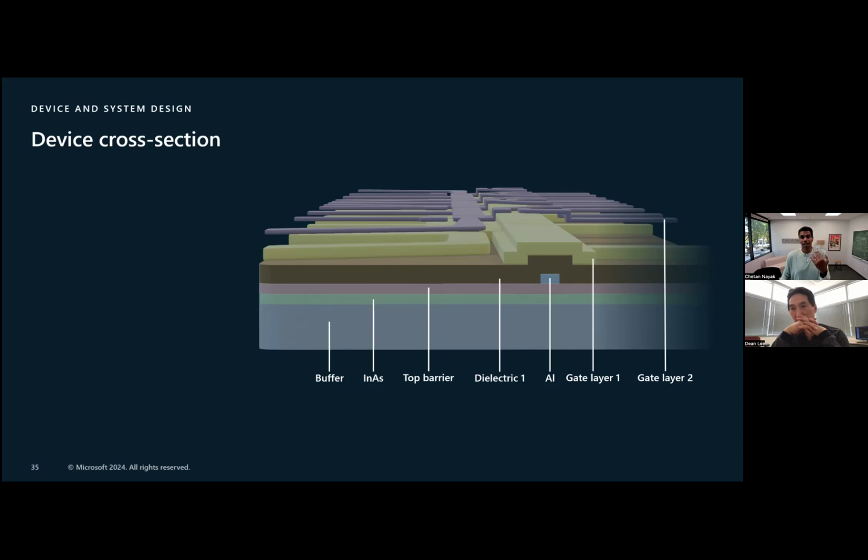So we need a healthy and robust interface that's relatively transparent, so that you can get electrons to hop into the superconductor and back. We want a lot of tunneling into the superconductor, but we don't want too much, because if the electrons spend too much of their life in the superconductor, then in the superconductor their g-factor is not 10, or actually it's not -10, it's +2, because in aluminum the g-factor is basically the same as in free space. So the g-factor will be renormalized downward from its really good large value in indium arsenide. The spin-orbit coupling, which is larger than 4 meV nanometer, if it spends too much time in the aluminum, will also be renormalized down.